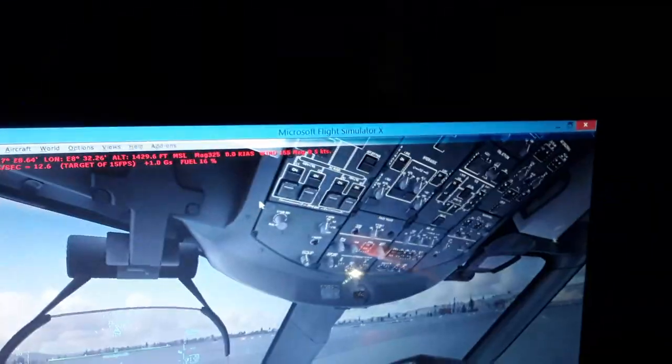So I'm gonna use now this information. You're gonna see the flight plan we have created in the primary flight display. We have the HSI, the horizontal situation indicator, with the graded display, and also we have the horizontal and vertical profile of the aircraft. As this flight, you can see the horizontal and vertical profile of the flight plan we created, so you can see where we are located, and also the takeoff. We're gonna use the runway, the cruise, descent, approach, landing, the flight path or flight plan or route of this aircraft. So you can see also the modes around here in the head-up display.